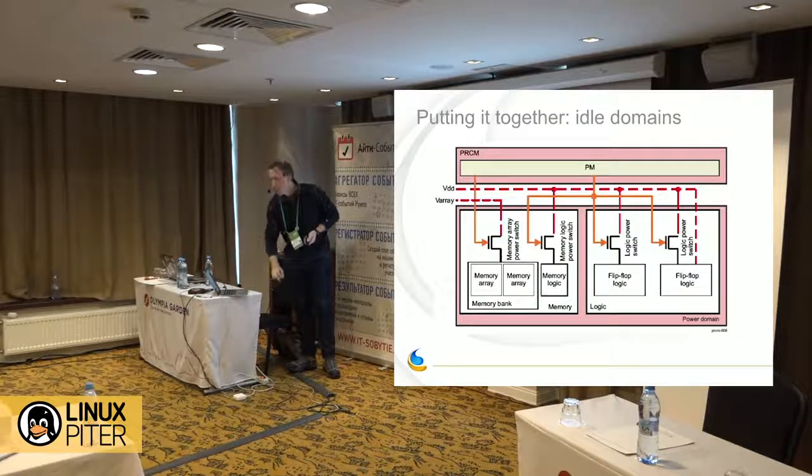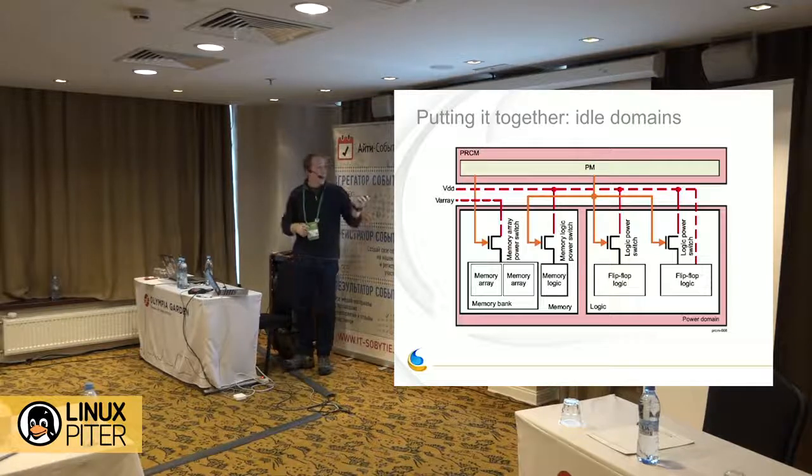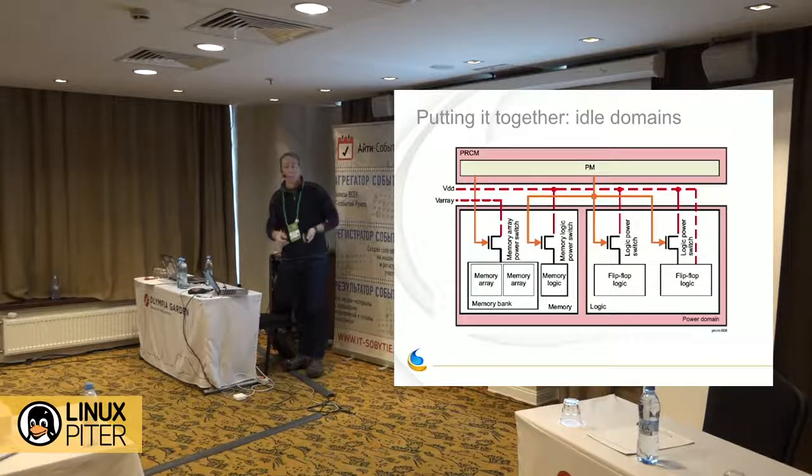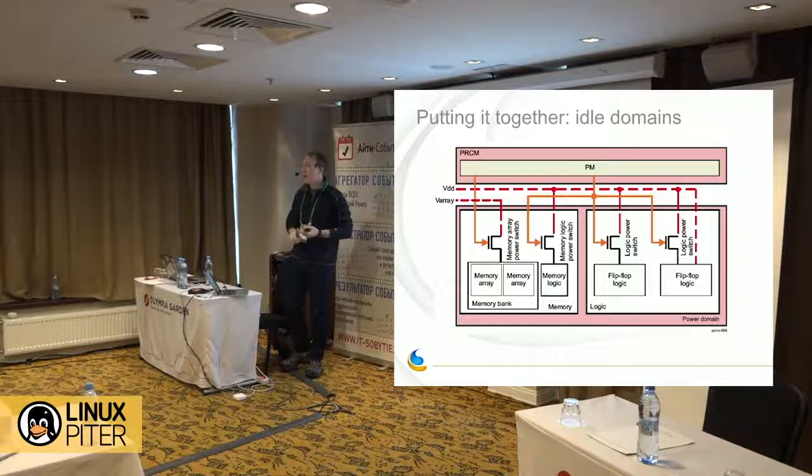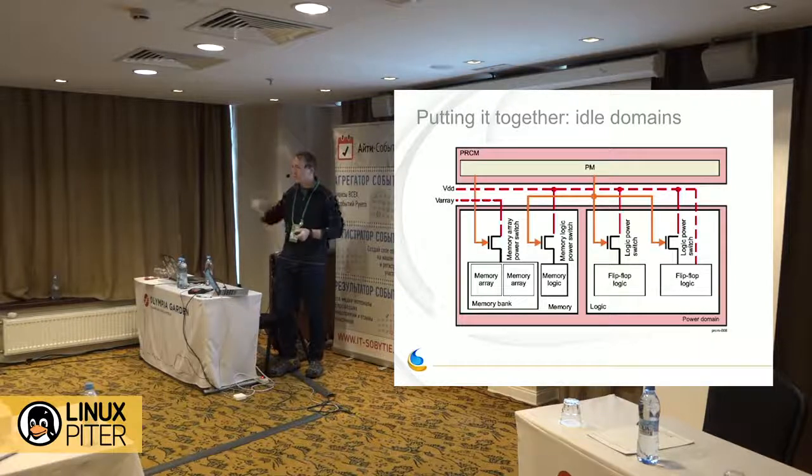The next level up, and there's no good standard terminology for this, but I'm calling these idle domains. A lot of times you hear about power domains, power areas, and what are these? These are basically areas on the chip where we have electrically isolated transistors, and you can imagine a power or an idle domain as being a container filled with a bunch of modules that you can idle all of them, and you can lower the voltage or totally cut power to these modules.